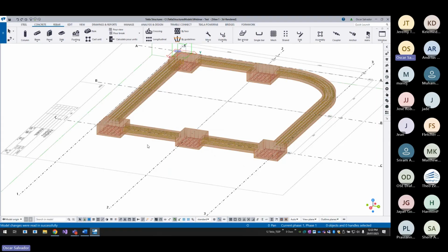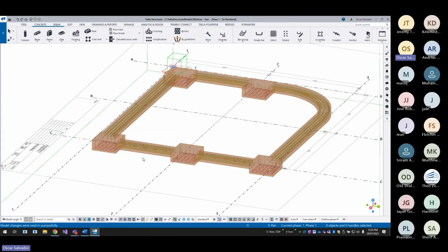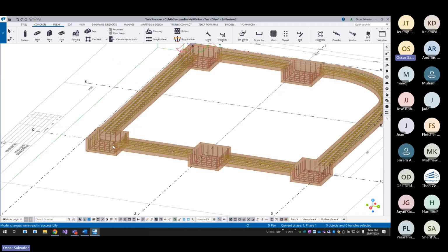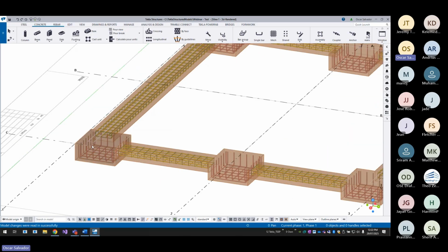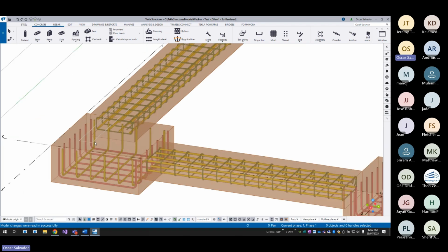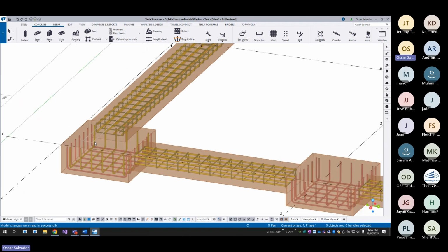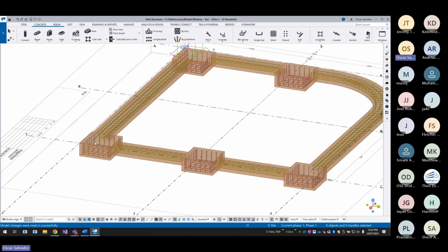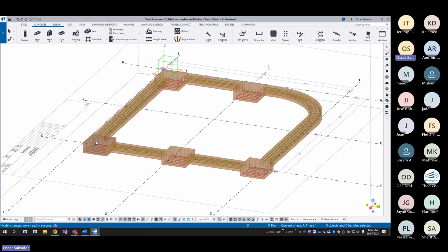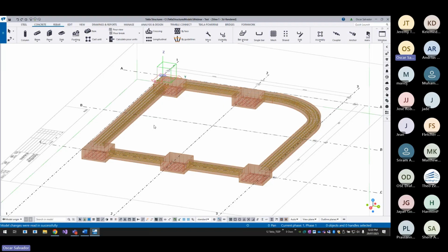We have a model here shared by Jeremy with an existing reference drawing, and you can see some foundation and strip footing already. Let us use the reference drawing to trace the precast panels. I love doing the trace in the 3D view because I can visualize the panels as they are created, and with proper snap and rendering switching, we should be able to do this.